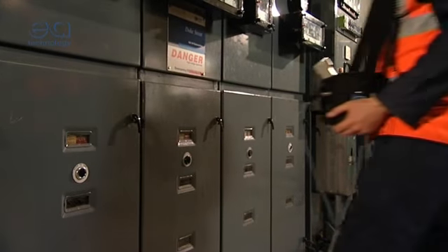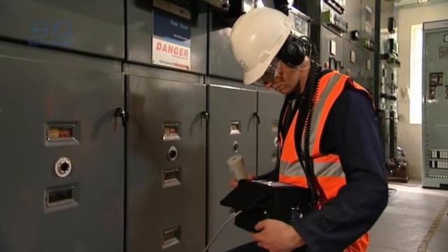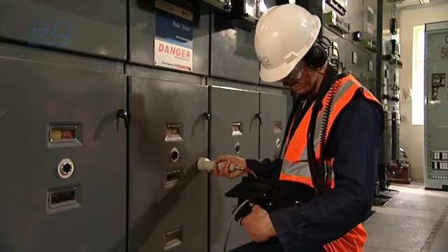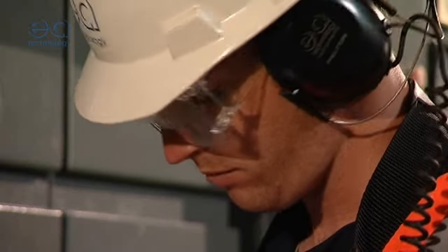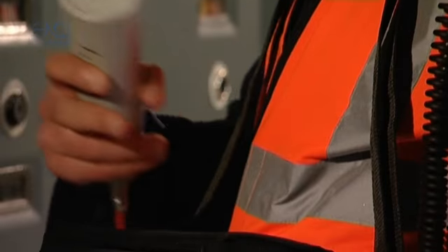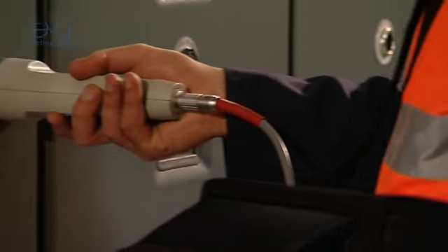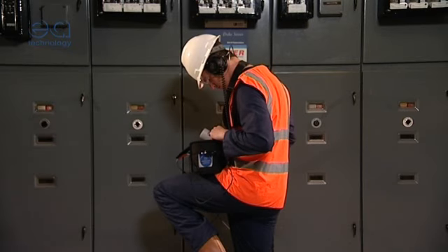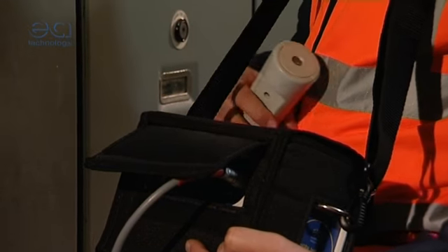You can also use the Ultra-TEV Locator in single probe mode. This measures both ultrasonic and TEV discharges to determine the severity of the PD activity. Options include using factory threshold settings for a quick survey to determine whether PD activity is at critical levels, or taking detailed readings of ultrasonic and TEV activity.